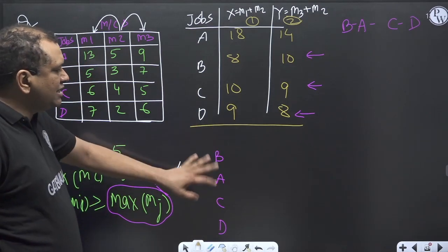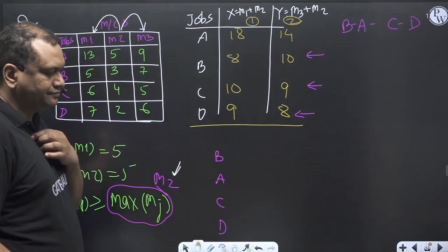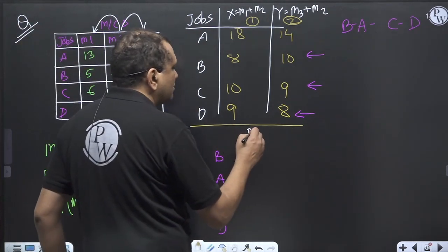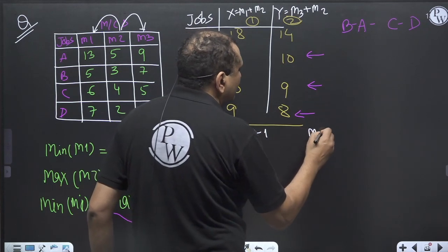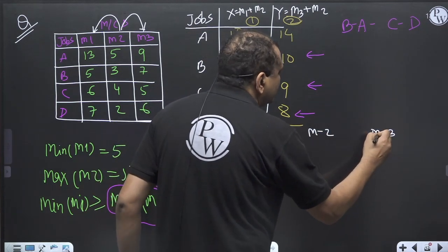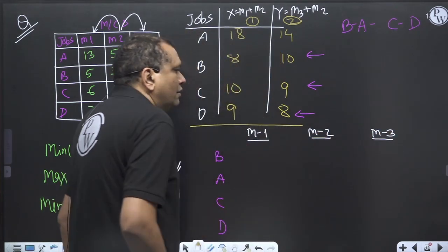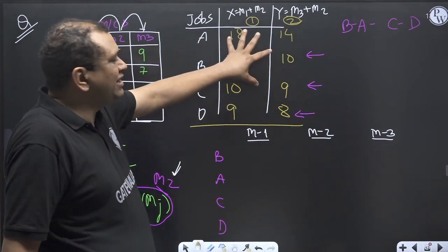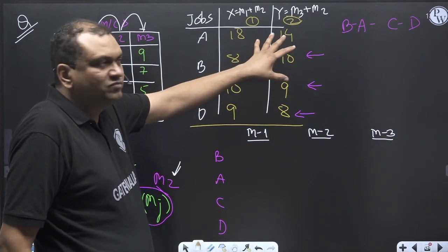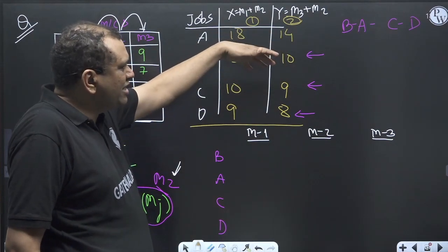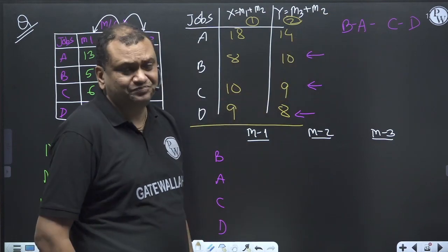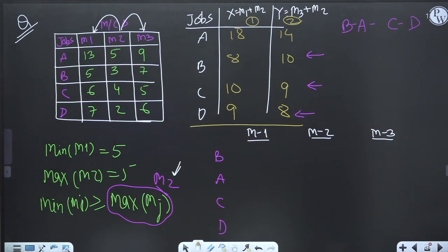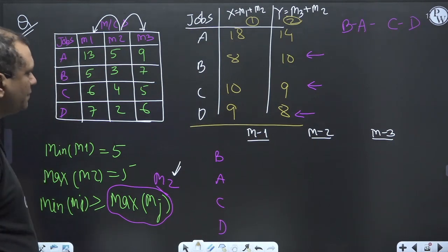After calculating the sequence, I will project it on the original matrix, machine 1, machine 2, machine 3. The cycle time calculation I will not do on the imaginary machines. The imaginary machines I have calculated only to get the sequence. This sequence I will project on the original matrix only. So now let us do this calculation.